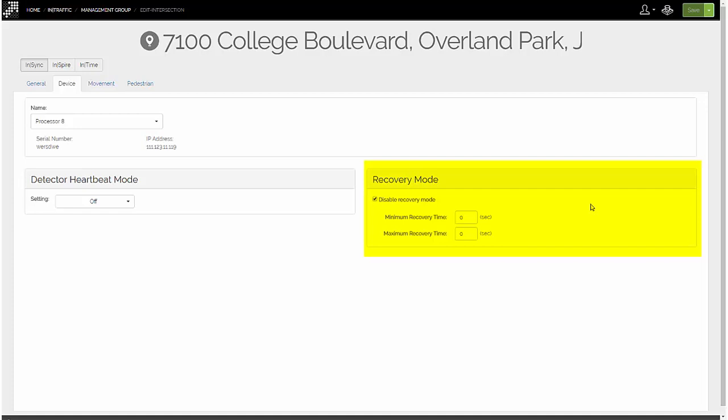You probably know what emergency vehicle and railroad preemptions are, but let's take a minute to discuss the concept of a watchdog interruption. The watchdog is InSync's method of servicing any phases that have been waiting for a long time. This could be caused by controller preemption, unintercepted pedestrian calls, unintended configuration problems, or incorrect controller settings.